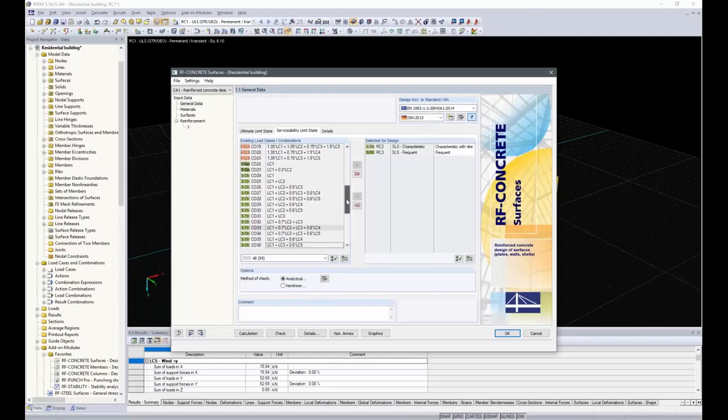And we use load combinations number 22 and 23 for the quasi-permanent loads, because the deflection analysis needs an unambiguous position of the loads, which can't be achieved with result combinations, and that way we have to use the load combinations.